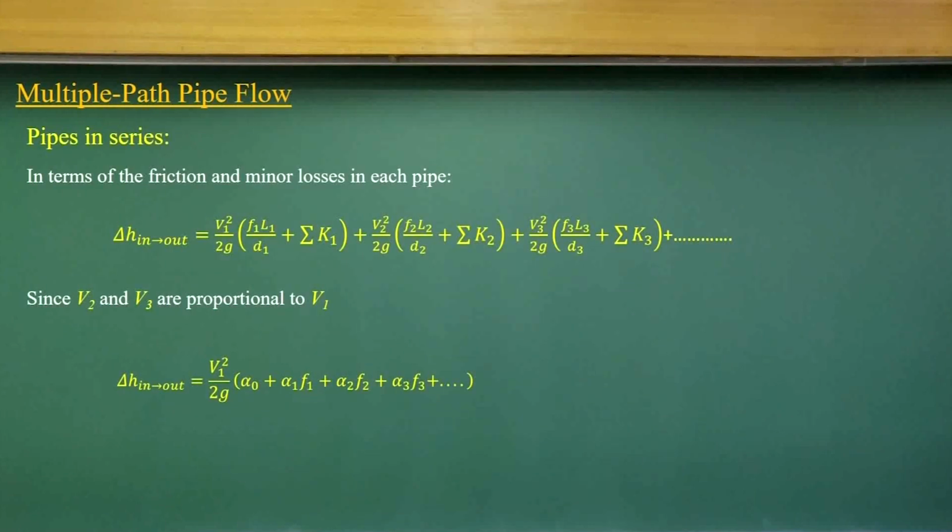But when you have pipes in series, please remember that you should always consider whether there are minor losses. There are major losses, which are the frictional loss component for pipe 1, and there will also be minor losses because of the change of diameter of the pipe, okay, there will be expansion or contraction, exit loss, entry losses.